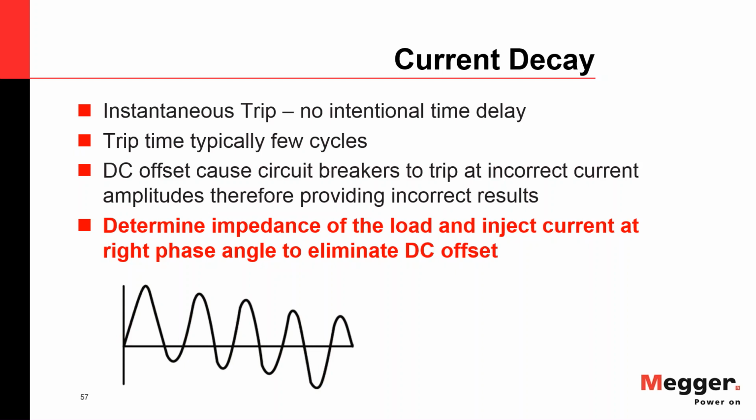There's means for adjustment, but the user always has to take care of that. What you have to do is the device that actually makes the current, closes the circuit, the gating device, you have to adjust the firing angle. And the way you do that, your current meter has to be able to measure true RMS, and it has to be able to measure what's called peak divided by square root of 2.